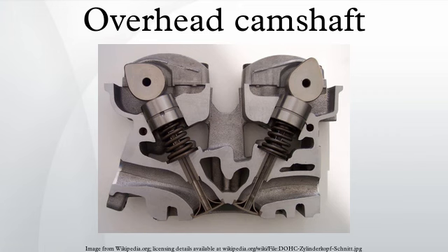Electrolysis and corrosion problems due to the bimetallic construction of the Crosley engine and the salt-based antifreeze then in common use led to a more traditional cast-iron block assembly version of the same engine in 1949. Used in Crosley's Hot Shot sports car, this small OHC engine won the first 12 Hours of Sebring race in 1950. The Crosley OHC was popular in H-modified racing for its higher RPM performance. After Crosley ceased automotive production, the engine was produced by several other companies for many years, finishing its life as the Barcat 55 outboard motor manufactured by Fisher Pierce, builders of the Boston Whaler boats.